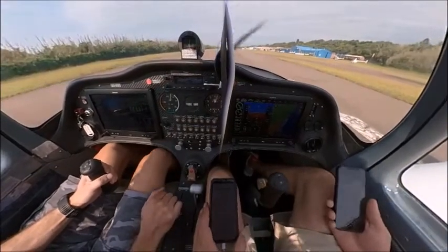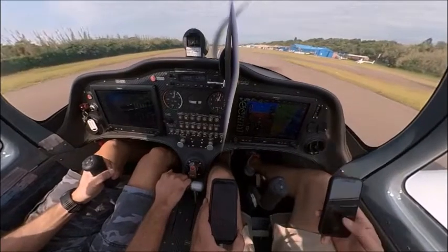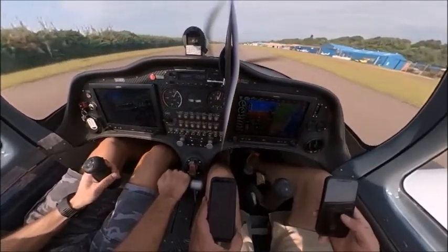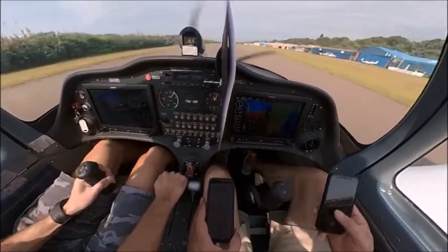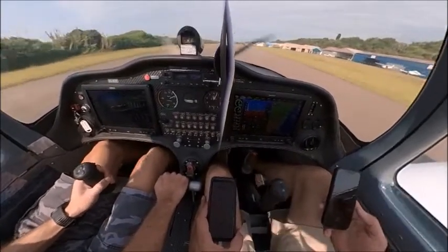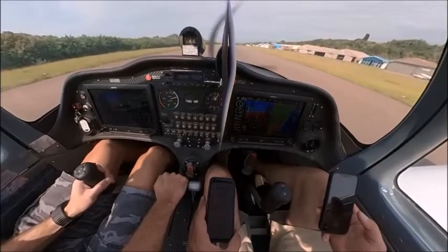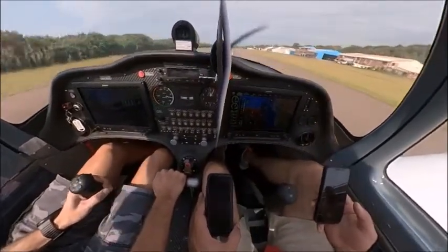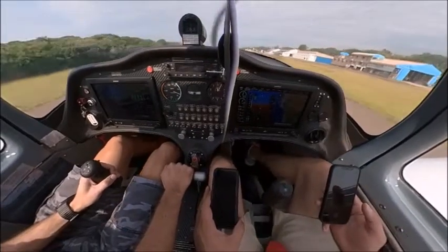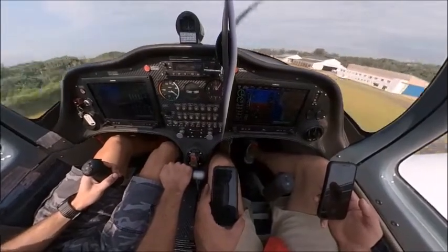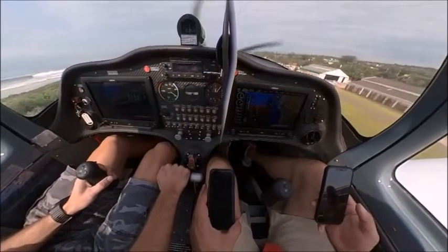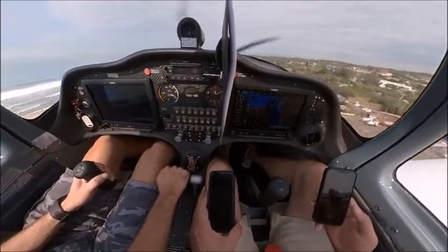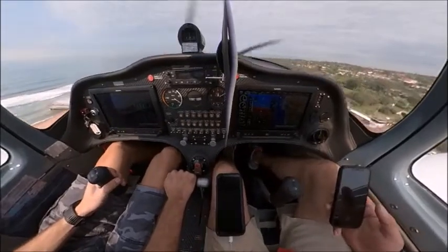Once we've taken off, the best climb rate will be at a velocity of 75 knots. In the event that we're still on the runway and there should be an incident that happens with the engine, we just reduce the power and vacate the runway. But after we've taken off, we will then have to perform an emergency landing. And this we can do on a beach along the coast over there. And the best glide speed for the Sling 2 aircraft is 72 knots.